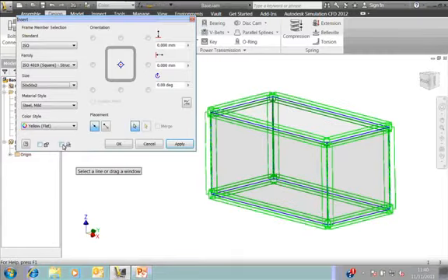The second one is relatively new. This gets the frame member's part number from the content center. Now this is actually very useful if you want to roll up standard lengths, common lengths of steel sections. So if I've got some box section, say I've got 4 of these a metre long, it'll roll these up into the parts list as 4 off a metre long, as opposed to giving these all separate part numbers, and obviously in the parts list you just have one of each. We're asked this all the time. It's quite useful to do this. I would suggest you don't use that button if you're using Inventor Professional with the item master, because that doesn't come through correctly at the moment.